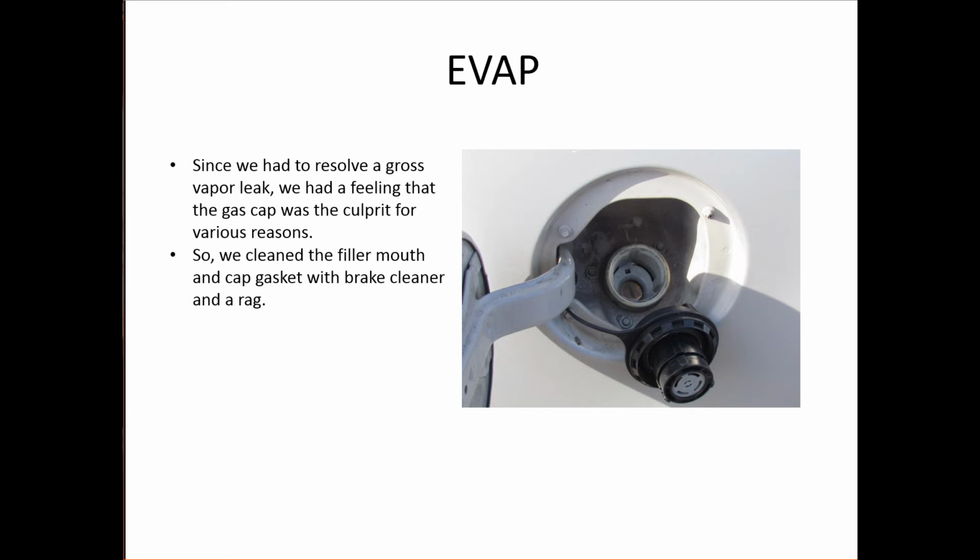So we went with that. We cleaned it with brake clean on a rag. We cleaned the lip of the filler, and then we cleaned the gasket in the filler cap and reinstalled it. The reason we thought this was it is his teenage son drives the truck frequently and might have been in a hurry and left that open. So we went with that one.